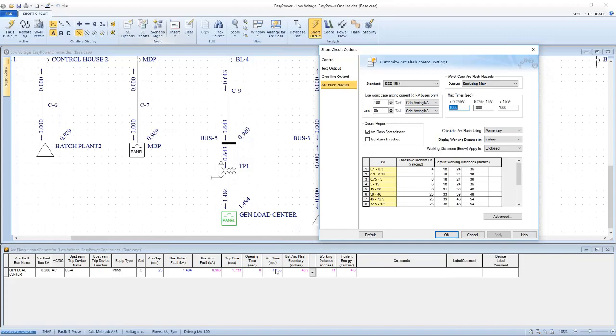And in this case, the calculation of the arcing time is 1.73 seconds, and it's only 968 amps. Testing has shown that below 125 kVA, 240 volts or less, even though the arc may be initiated, it will self-extinguish in less than 300 milliseconds. So with engineering judgment applied to this situation, I feel there's literally 100% guard band in this situation to limit my calculations to half a second.